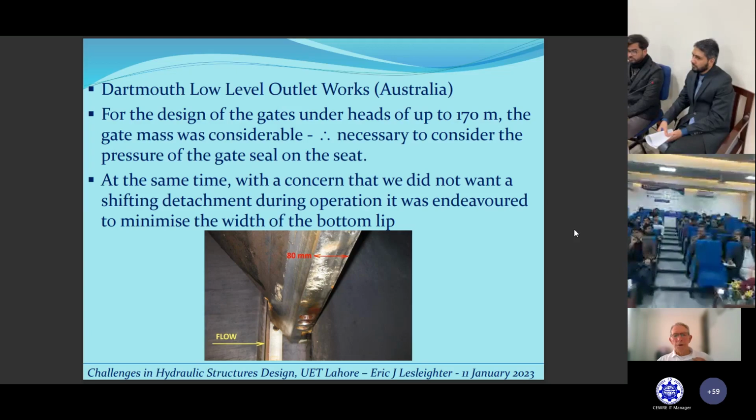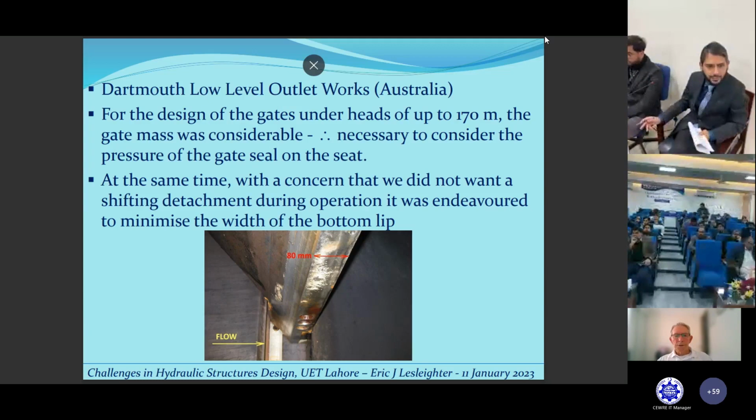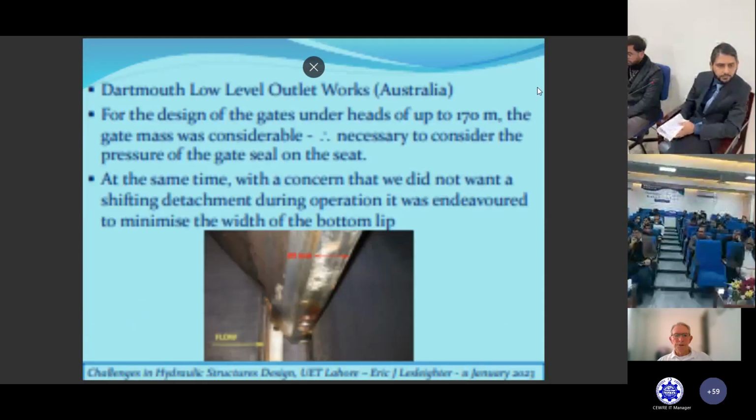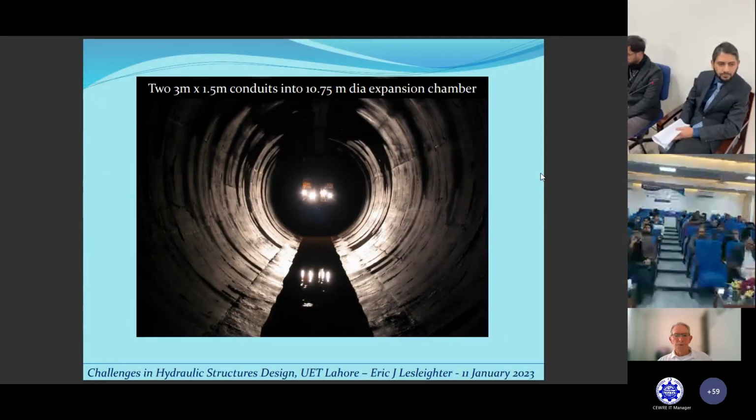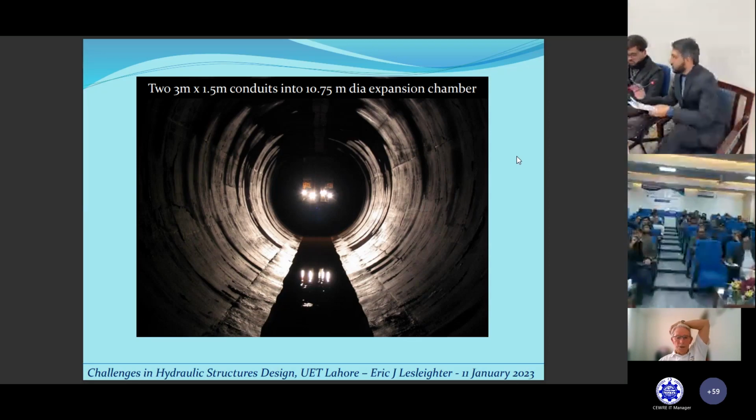Cavitation: when flow bends over a shape, streamlines don't follow the shape. They tend to go together or they separate. So there's an increase or a decrease in the apparent depth of flow. And you can get vapor pressures if the pressure drops low enough, and you have what's called vaporous cavitation. Cavitation bubble collapse is a violent process that generates highly localized, large amplitude shock waves and microjets.